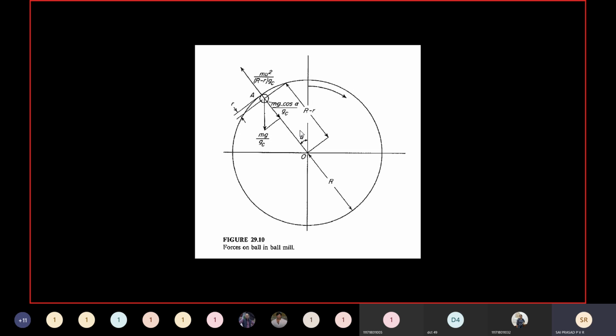As you go on increasing the RPM, a stage will come where the grinding medium rises to a maximum height, and from this point we are supposed to break the contact. The contact is broken when the gravitational force becomes slightly greater than the centrifugal force, and thus from this maximum height it falls on the object. If an object is present, it will take the blow of impact. The speed at which this is rotating is called the critical speed.